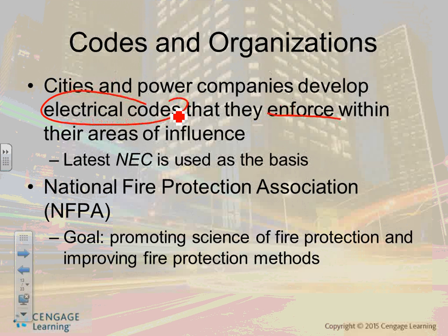The first thing you do, guys, is you contact the state or the city, typically the city that you're in. Ask them what type of electrical code they are enforcing. Are they enforcing the NEC code book only, with modification? What else should I know?